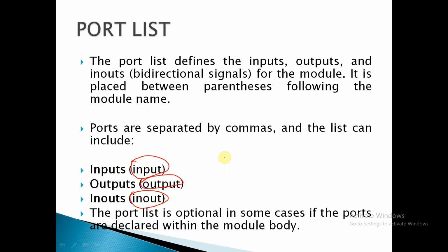For example, in the case of test benches, we are not going to give any ports. For only designs we are going to give the ports. The test benches also we will see. When a variable is working both as input as well as output, we are going to give it as inout, like a bi-directional bus.